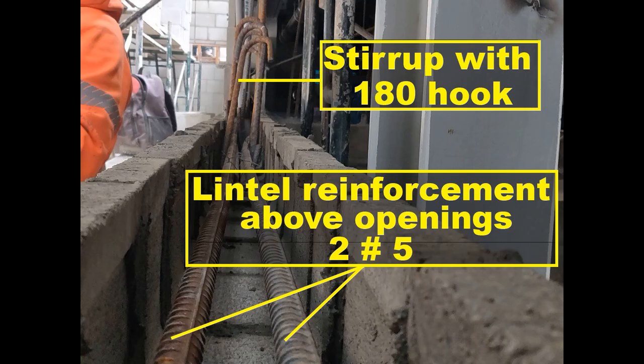In the attached picture you can see section of lintel at opening with stirrups with 180 degrees hook and adequate reinforcement clearance. Typical lintel reinforcement is 2 number 5 or 2 number 6.